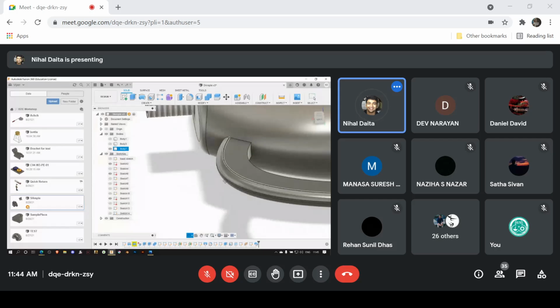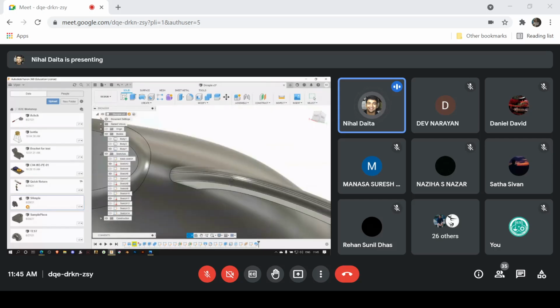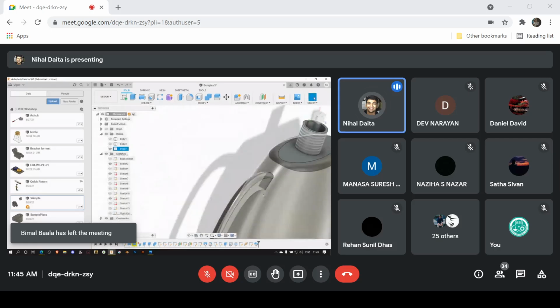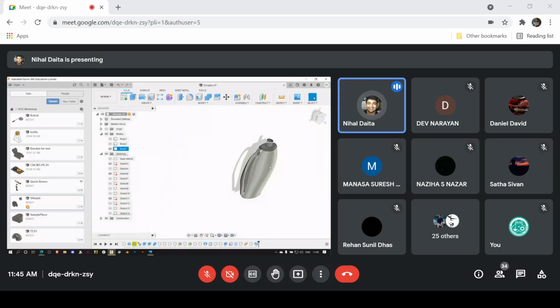As you can see, the change I made in the sketch has been carried onto the handle as well. As I told you earlier, since there is this timeline approach, if you modify a feature in the past, that is carried over to the end.